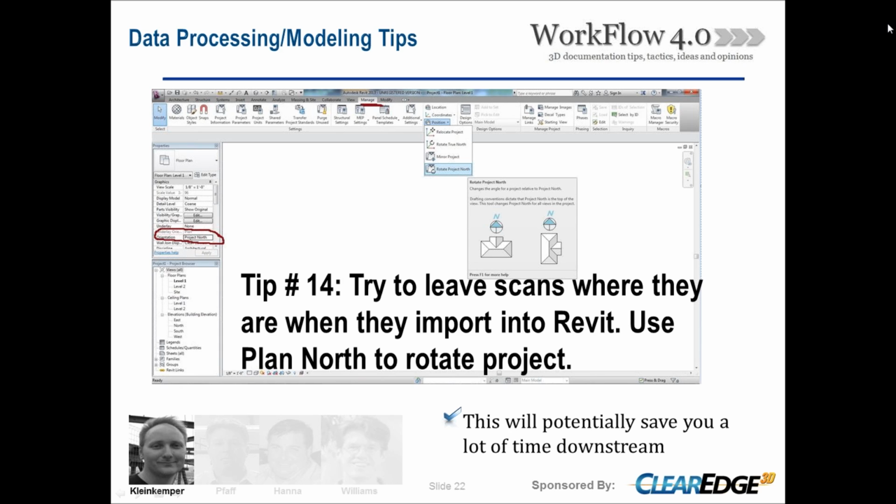And then over on your properties for each view, it's typically set to project north once you do that, but you may have to double check that, where I've circled in red to the left. That will help you immensely downstream if you bring in any more scans later that you may have thought you didn't need, or when working with a program like Edgewise, all of their pipes and objects will come in right into place if you haven't moved those scans and if you use this method.